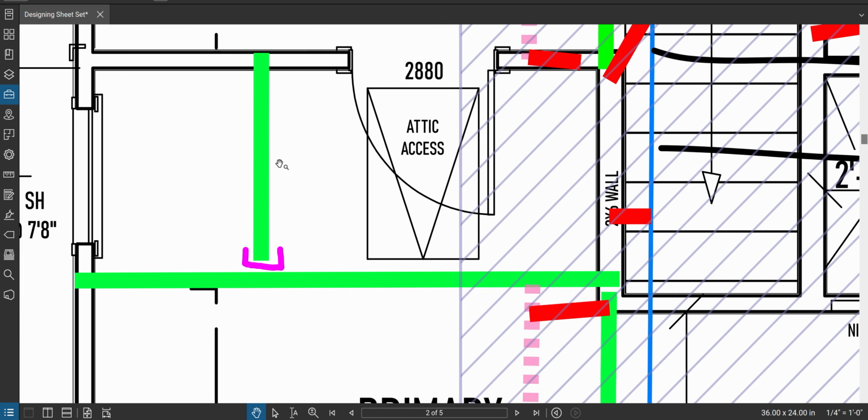This is not super important. I'm just kind of averaging, saying it's on top. There's no crazy side loads. Ceiling, no attic, is going to be 5 and 10. And this is going to be ceiling. Okay, then I am going to add a load. Uniform, pounds per square foot, whole length. Tributary width, let me grab that from my drawing.